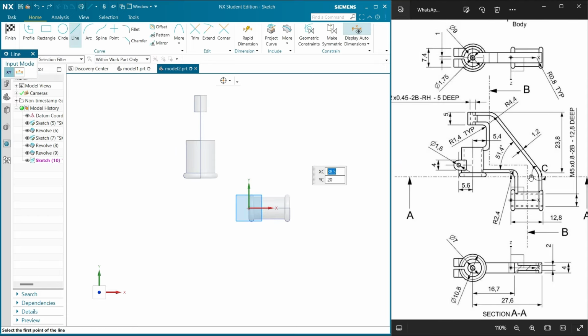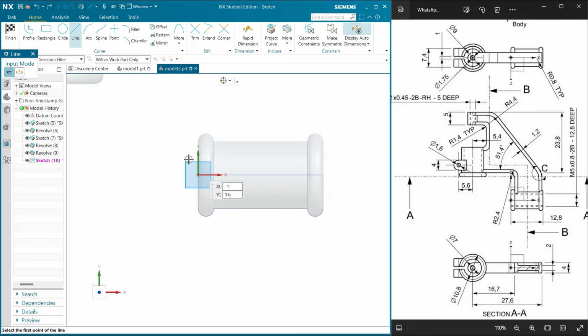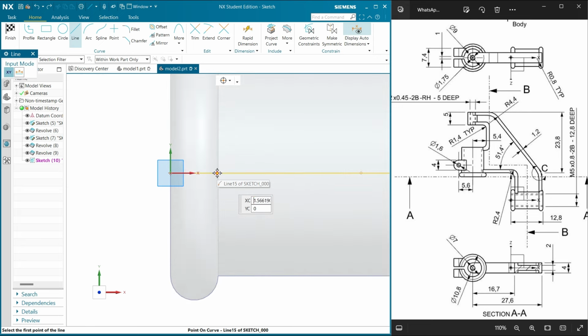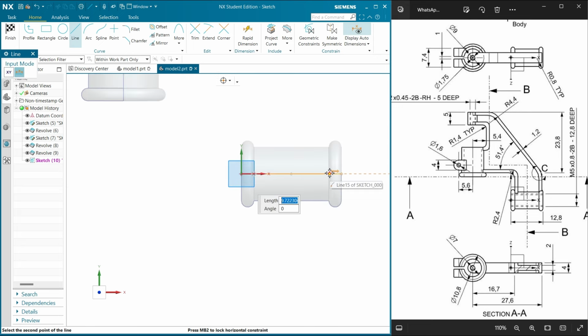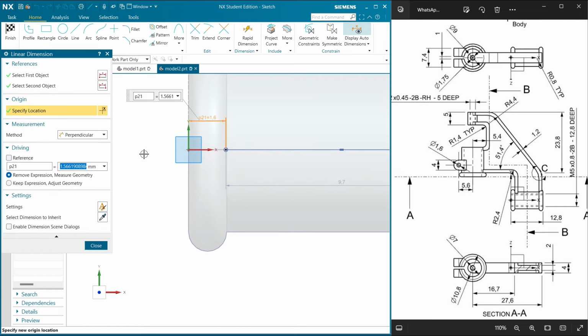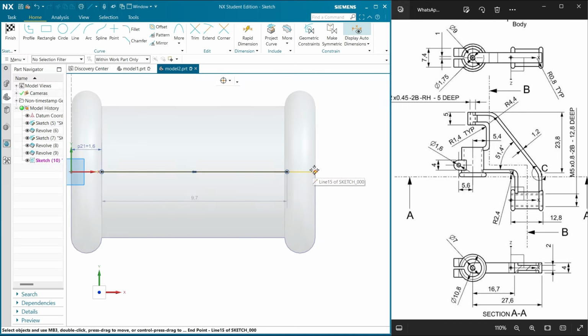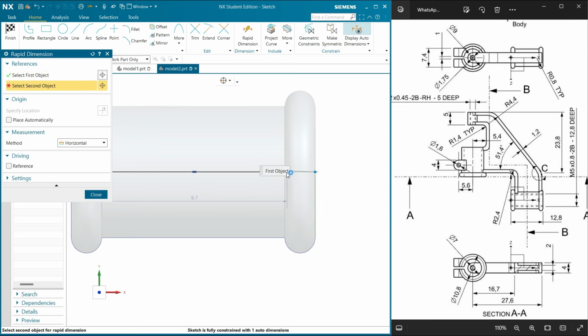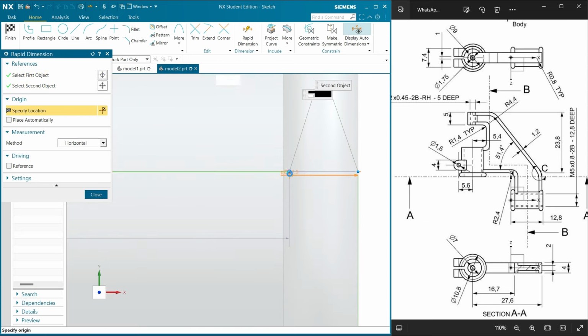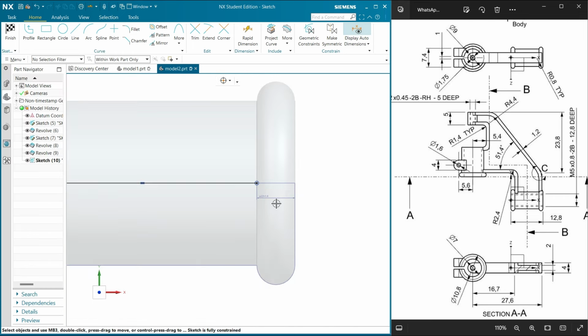Okay, now we're going to draw this. So let me first make a line here at the center. And that line should start from there until here. Just to be sure, the distance from here to that line should be 0.8 times 2, since our radius here was 0.8. And also from here to here should be 0.8 times 2.